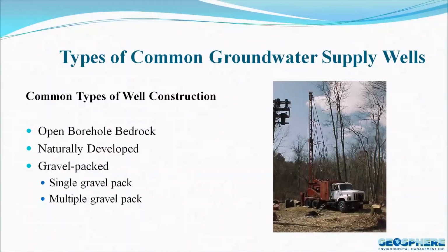So, some types of common groundwater supplies, Ted talked a little bit about them. We looked at the open borehole, which is simply a bedrock well, naturally developed ones, and those can be gravel packed ones, which can be single gravel pack or multiple gravel pack. We typically look more at the single gravel pack these days as opposed to multiple ones.